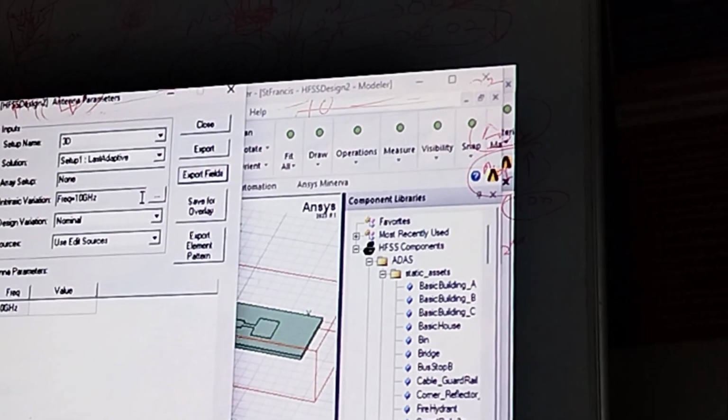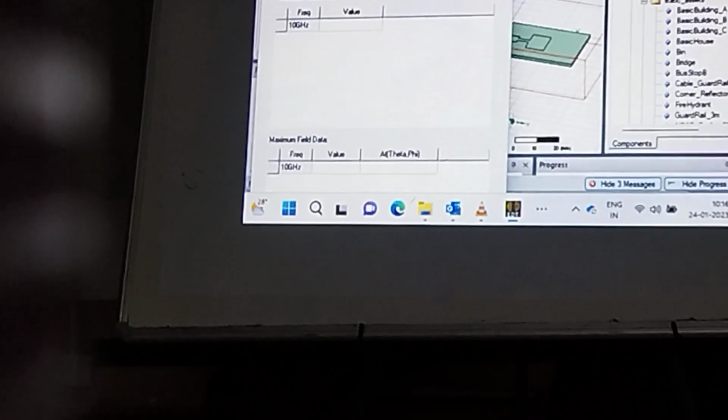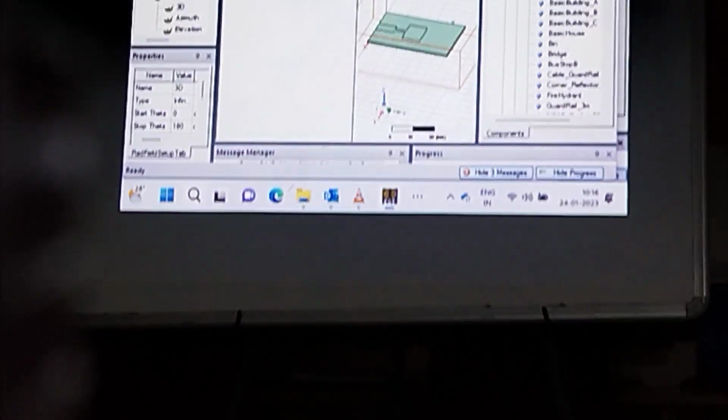Okay, actually this has not run, and the radiation has not been generated, so it is not saved. So basically we save the far field data in this way. Let's suppose we are going for EMIT here. To support this, let us start with the insertion of a new EMIT design. So you can go to project, and you can see an option, insert EMIT design. Just give it over here.